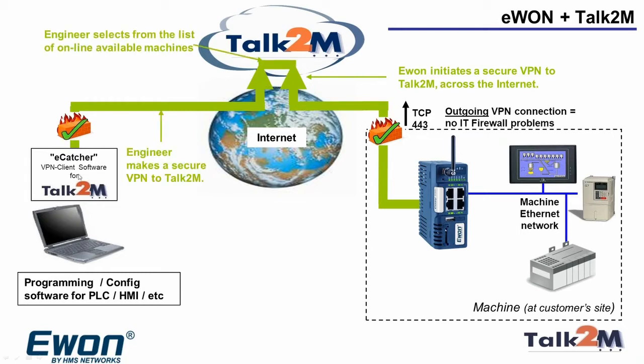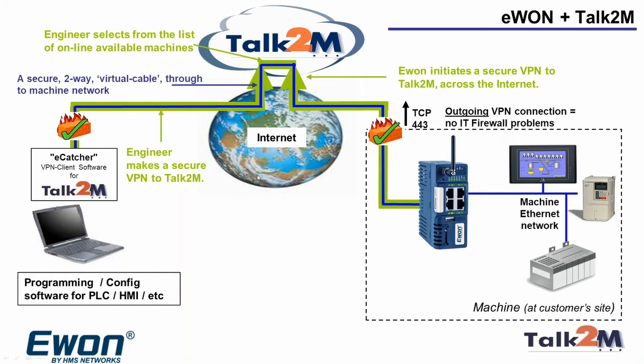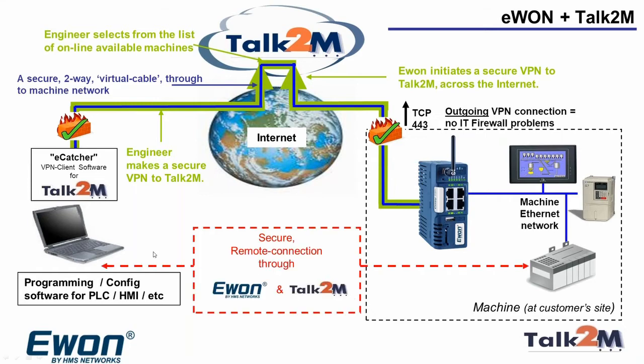Once that's happened, you can then see a routed path from the laptop on the left-hand side through the eCatcher software, through the Talk2M cloud, through the box to reach the devices behind the Ewon, which on the right-hand side are the devices that the engineer wants to connect to. So once that connection is established, you can then run the PLC programming software as if this laptop is over here on the right-hand side, as if it's on the end of a direct connection to the inside of the panel. And as we looked at last time, that's the core functionality of all the Ewon products, the Cozy, which we looked at last time, and the Flexy, which we're looking at today.